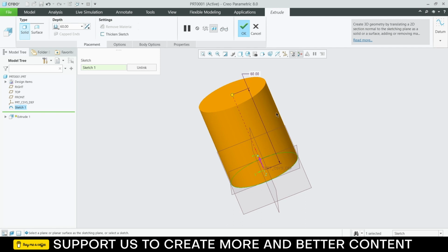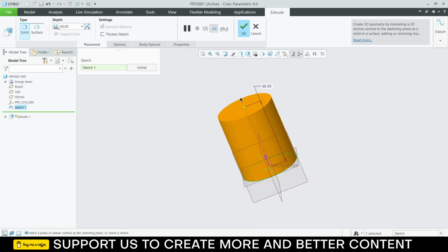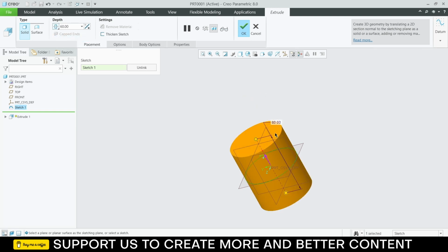Now somebody says, hey, I want to extrude in the opposite direction. So click on this icon. It is now in the opposite direction. Now if I click here, other options are there, symmetric and to reference. So watch carefully. This is the plane where I have drawn the sketch. Suppose I want to make it 60 mm long, but 30 mm this side and 30 mm at the bottom side. So I will click here, click on symmetric. Notice the total length is 60 mm, with 30 mm on this side and 30 mm on the bottom side.